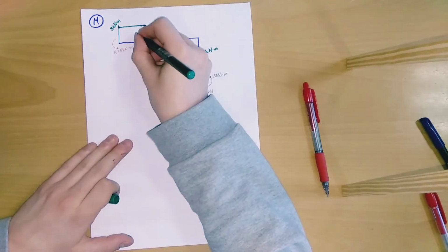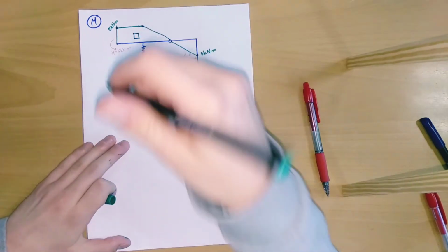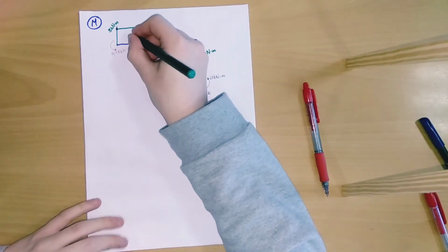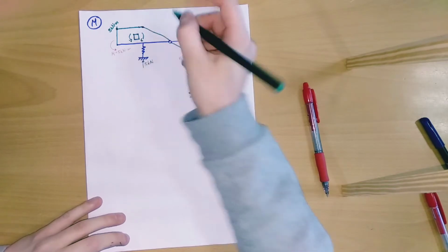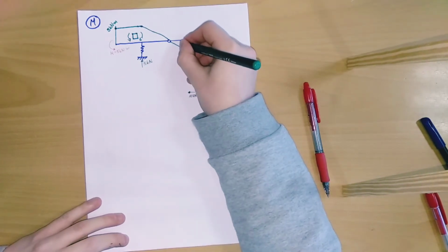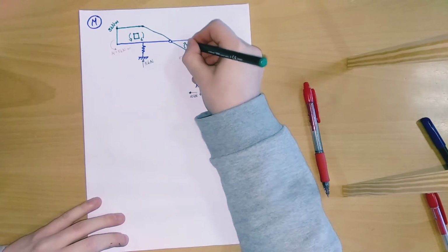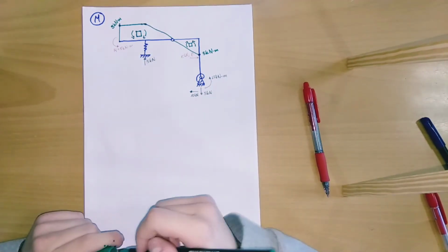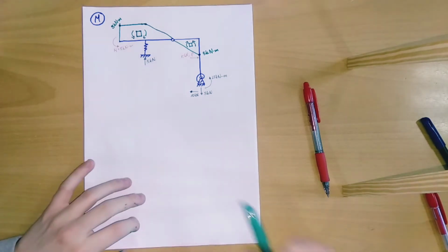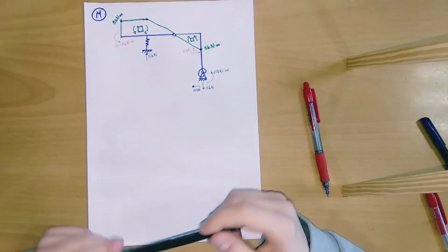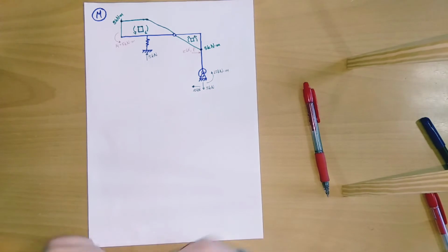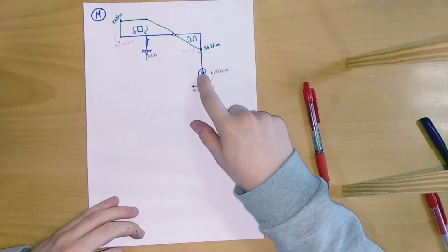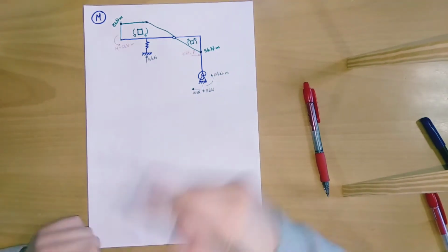In this part, the upper part of the beam is going to be under tension, and in this part, the lower part of the beam is going to be under tension. So that's the first part of the frame, where we have the value of the bending diagram. Now we are going to start from this point to calculate this vertical part.